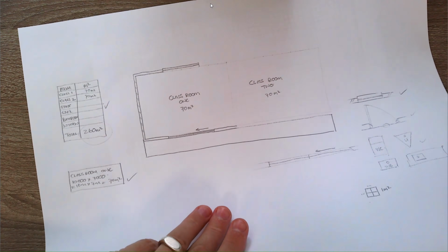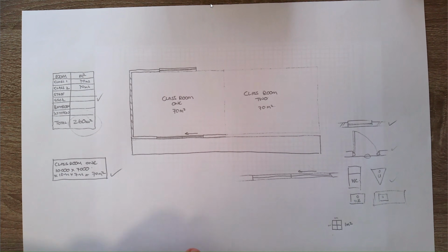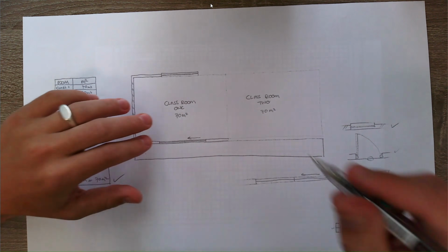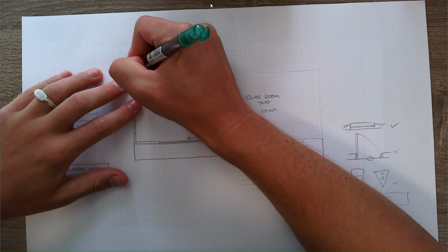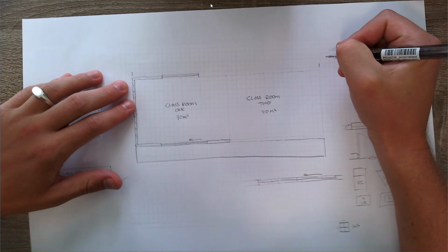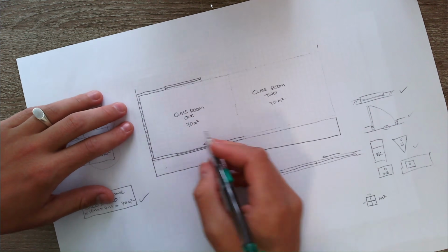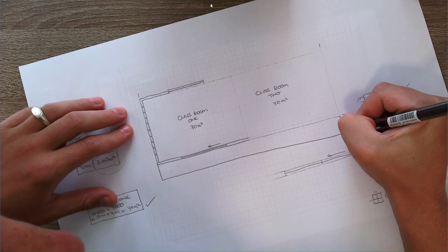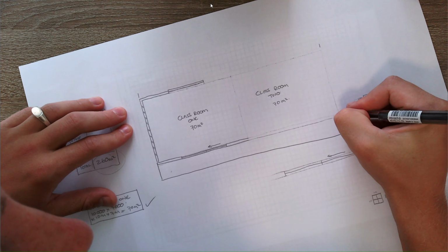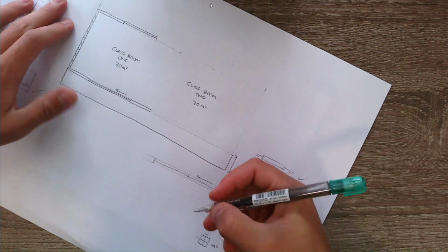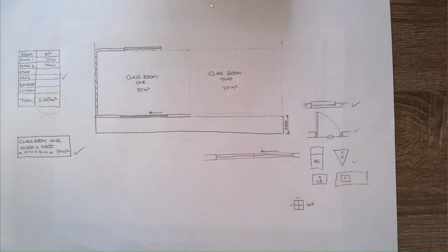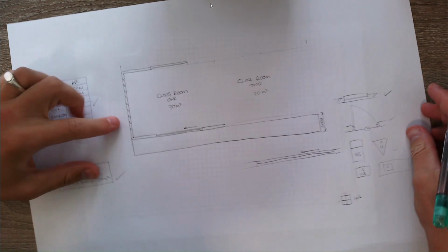They've also specified that you need to give primary dimensions and labels. If you label each room, you'll get your label marks, but you need to give primary dimensions. That means the big dimensions, length, width. You can give a few of them. I would put in 5 dimensions. We know from there to there is 2,000. They specify it in the scenario that the walkway has a width of 2 meters.